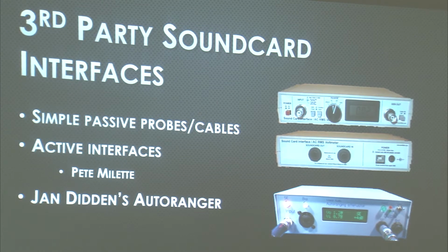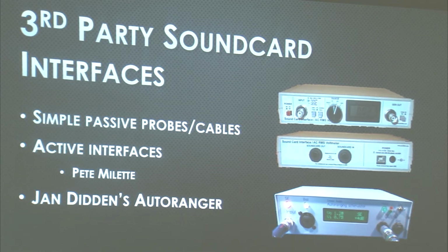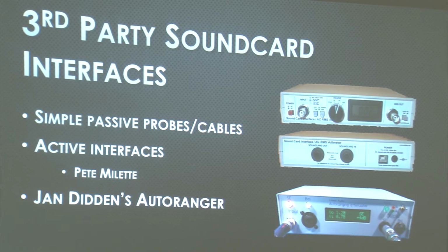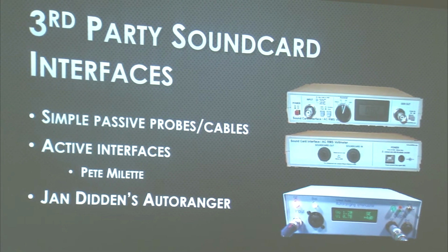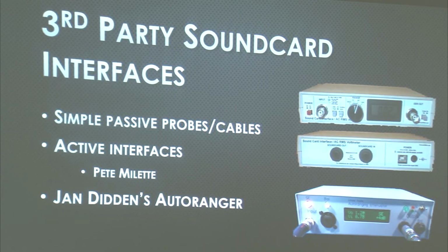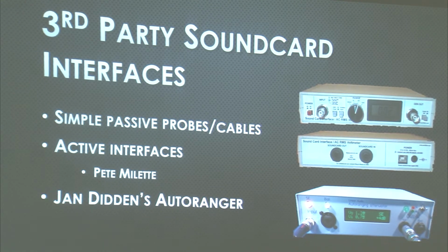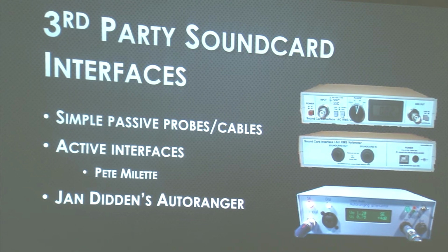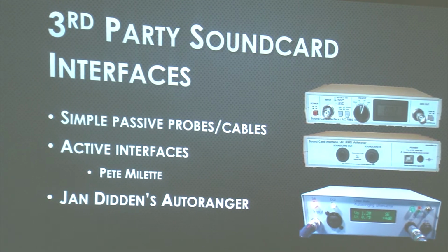It will just work. It runs off of USB power. It uses his silent switcher, so it has very good low noise and good distortion performance. But you need a good power supply to run it. And that means you need to really use an external USB source. If you plug it into your computer's USB to run it, as I learned the hard way, you will get noise and common ground issues because the ground on that box and the ground on your computer will be shared. That's always a problem. That's why you need these things with the differential inputs.